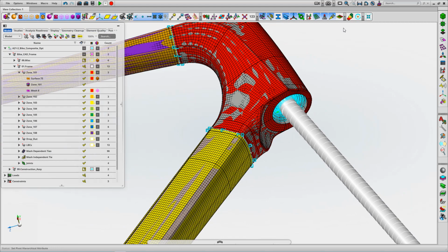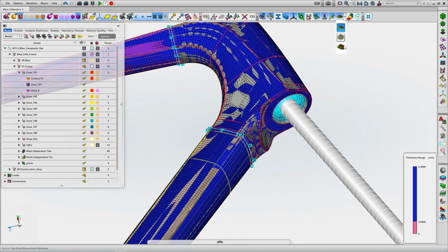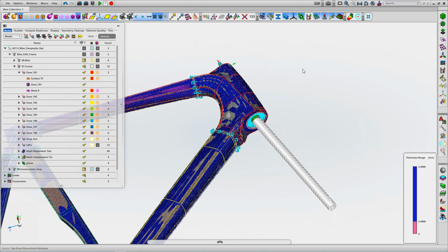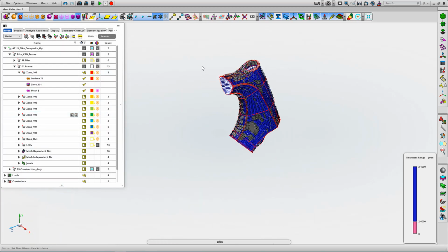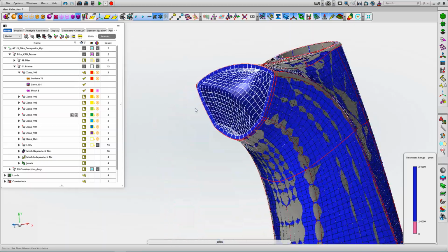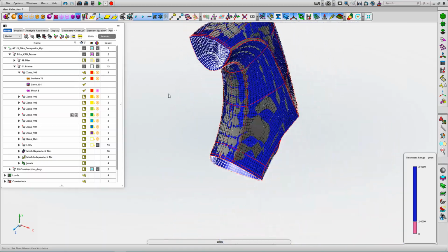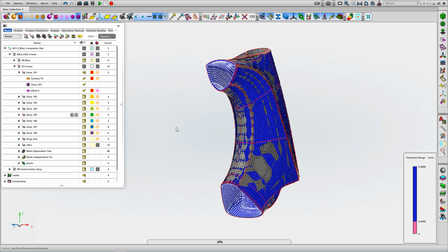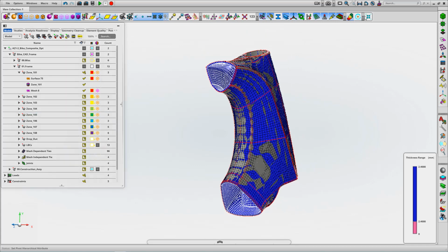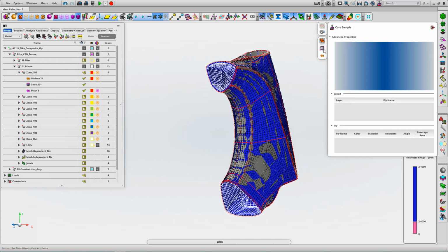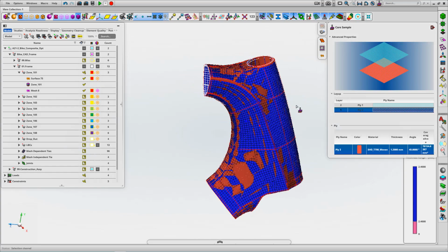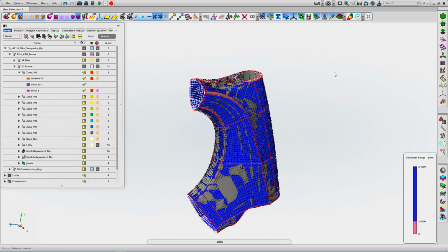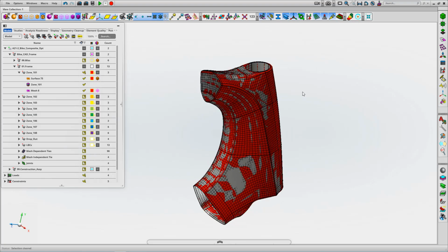Okay, so we'd repeat that for all of the zone definitions, and then we can show a map of the thickness plot. So we've got a uniform laminate here to start off with, and we can see our thickness going inside the outer surface, as it were, and again reflective of our build sequence within the structure. We can do what we call core sampling, so we can cycle our way around the structure and look at our ply definition and the coverage for discrete regions.